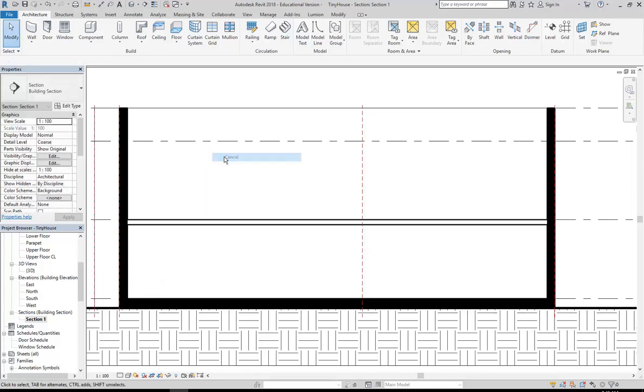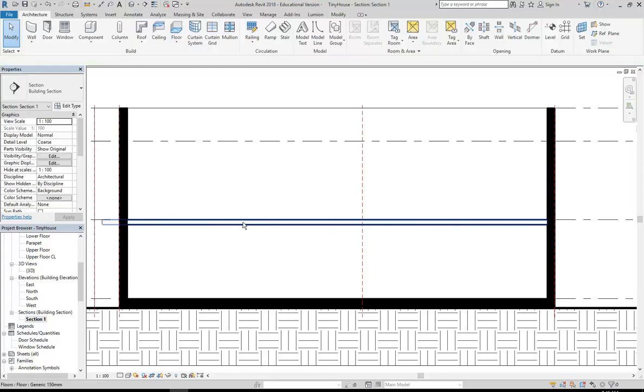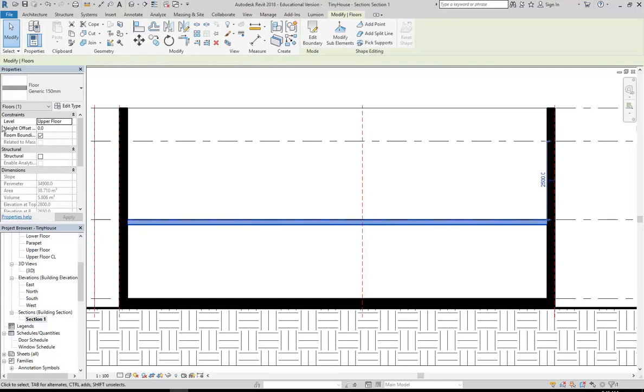So with this project, you're allowed to go below the minimum, but try not to go too far below 2400, if you can help it. For bathrooms and kitchens, you can go down to 2100. But for living spaces, it is supposed to be 2400, but because the existing building is already below that, again, you can go a little bit below, but again, not too much. So that's why I'm putting in a 150 floor, just to help you work that out.